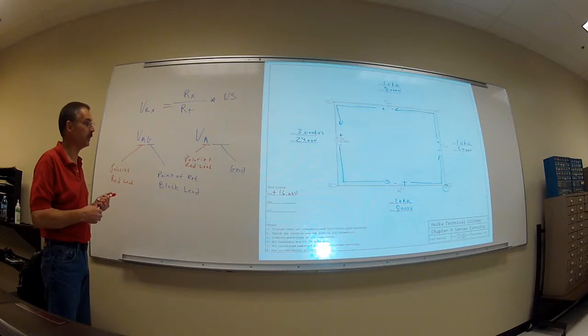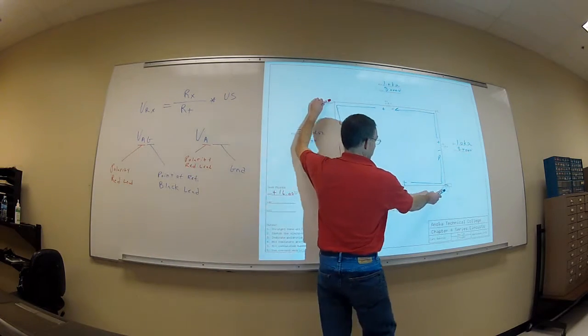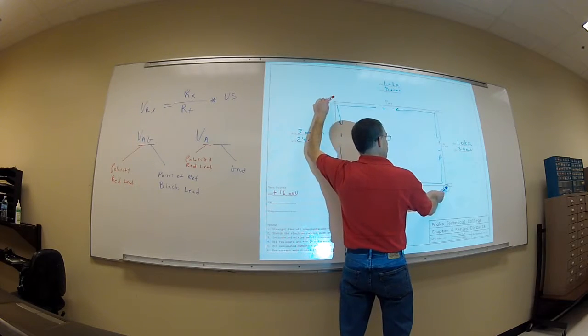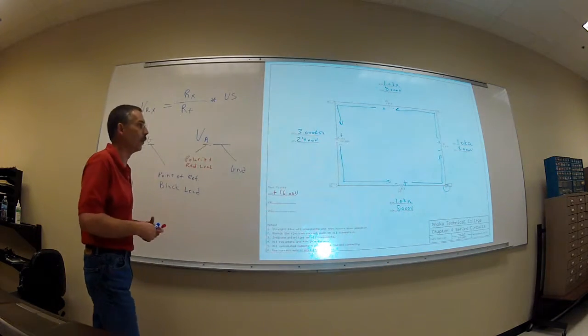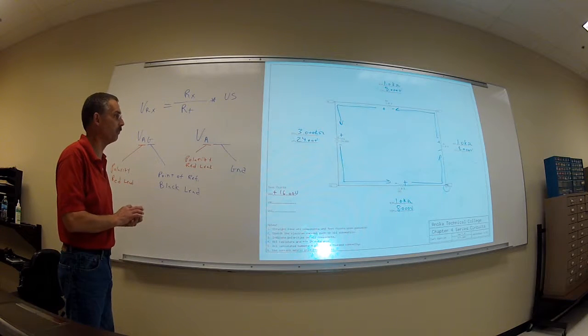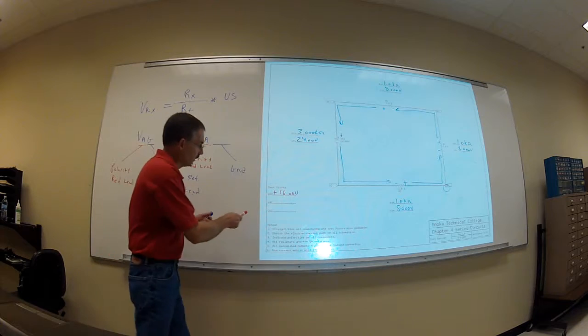Then that's when our troubleshooting kicks in. But if I just come in and say, yep, I got positive 16 volts there, I check all my test points, and everything matches up, then I know that circuit's working. It's probably something else then. All right, so let's take a look at the second one.